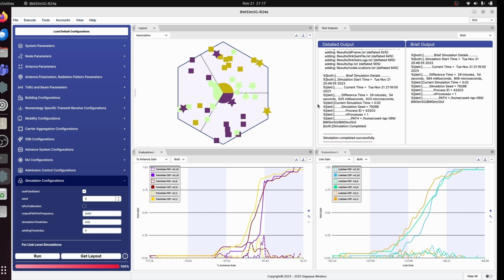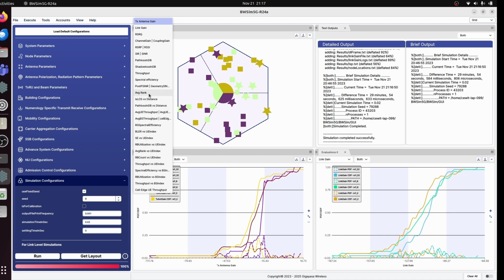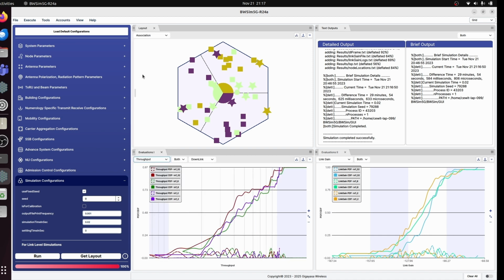Okay, now that the necessary simulations are completed, let's take a look at the throughput performance of these three RF chains. We filter on the CDFs alone. The regular rational thinking is that when you increase the number of RF chains, you expect an increase in the throughput. If you can see here, the number of RF chains equal to 32 is clearly outperformed by both the number of RF chains equal to 8 and equal to 2. So there is something that causes the deviation from the usual rational line of thinking.